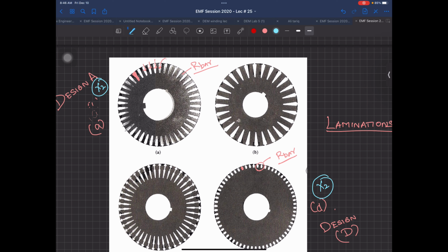Just as you had a stator leakage reactance, I told you that it will be a little larger than its counterpart in the transformer because it stays inside the iron core, and the one which goes towards the rotor is actually of our interest. So the one which remains inside the stator core is actually jX1 over there.